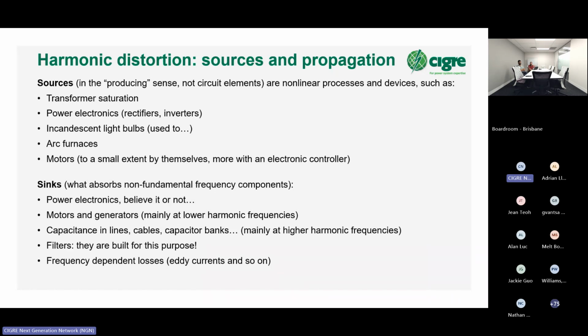It will be more likely that the energy at higher frequency gets dispersed in heat. So your grid looks, we can say, more resistive at higher frequencies because of this phenomenon of frequency-dependent losses, also called eddy currents. Again, I don't have time to explain in detail, but there's lots on the internet on this.